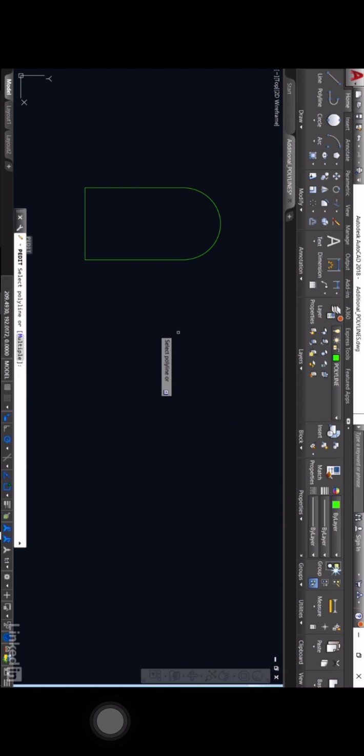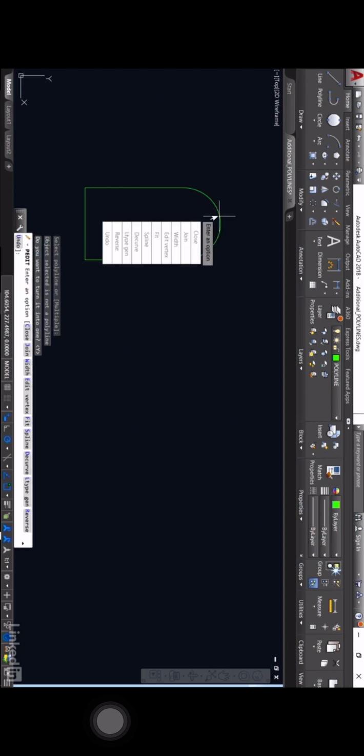So just press enter and it will prompt you to select a polyline, or as you can see on the command line, multiple polylines. Select any line or arc in this shape. I'm going to pick on the arc itself. It now says, do I want to turn that arc into an individual polyline? Well, yes, I do. So I press enter there to accept the Y for yes. Then I use join on the polyline edit menu that comes up. So I click on join.